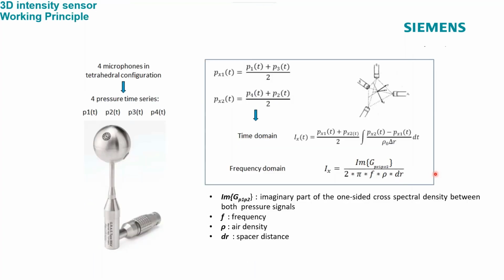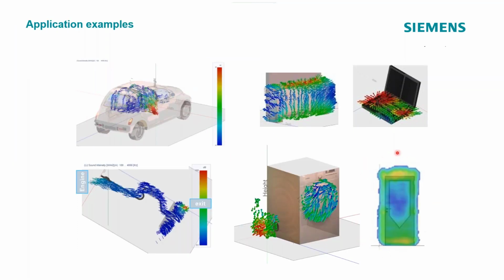If I was to show the accuracy of the tool, we're going to use 4 microphones to calculate the intensity, which allows us to hold this in any orientation as opposed to normal to the surface, like Raj said. So if I'm doing development and I want these type of results quickly, as opposed to the more laborious traditional intensity probe test that we've talked about, I can use this tool very quickly to get some intensity results for the source localization to look at what parts of the test object I want to go after to reduce the noise. That's kind of the sound brush in a nutshell.